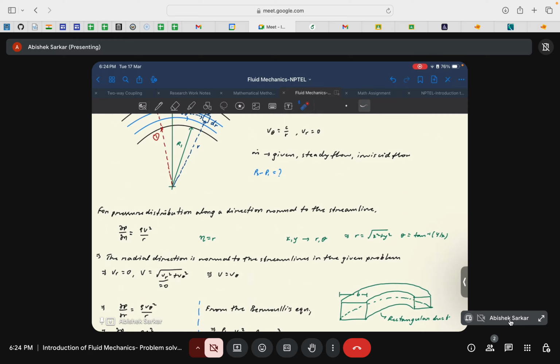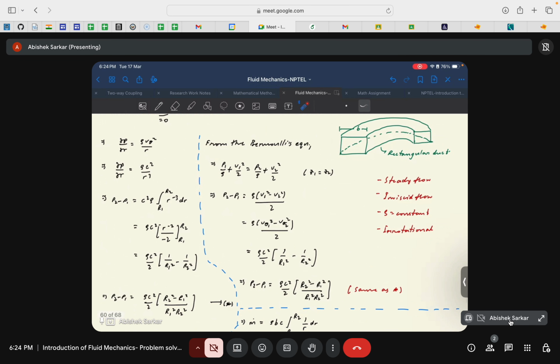It is irrotational. I know it, because this is an equation of a free vortex, again a higher terminology I don't think I should be using right now. But you can easily say that this is an irrotational flow. You can also just find del cross V. Remember you have to do it for a cylindrical coordinate system, so you need to find the respective equations for the nabla operator. Once you do it, you will eventually see that this flow is irrotational.